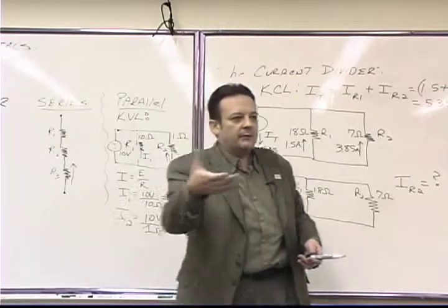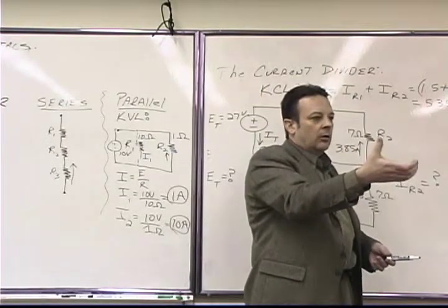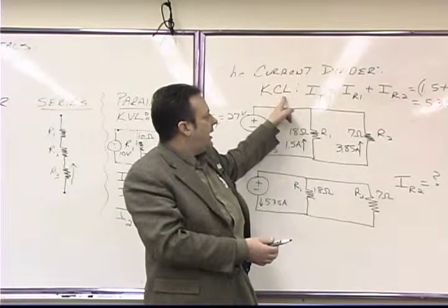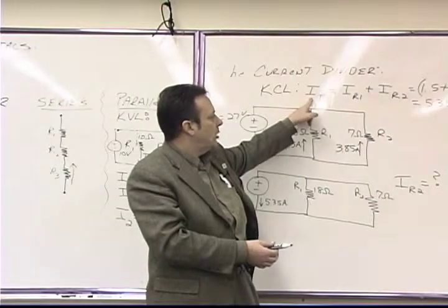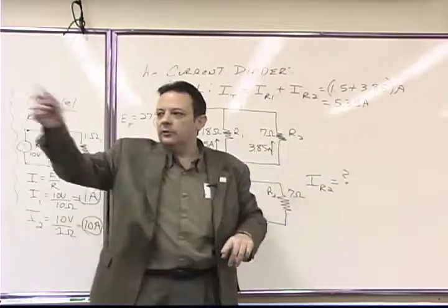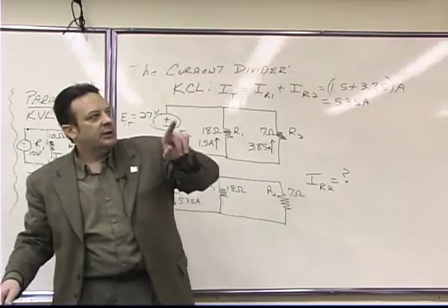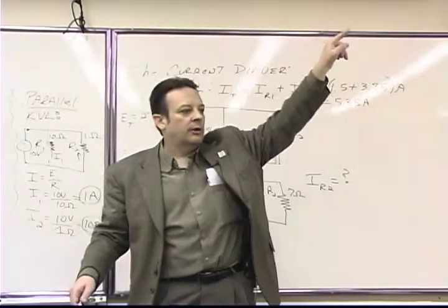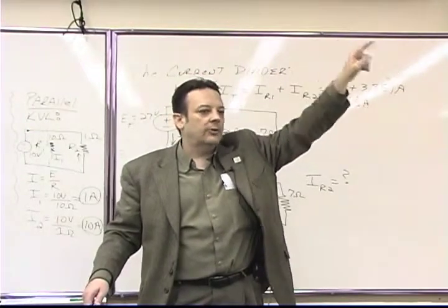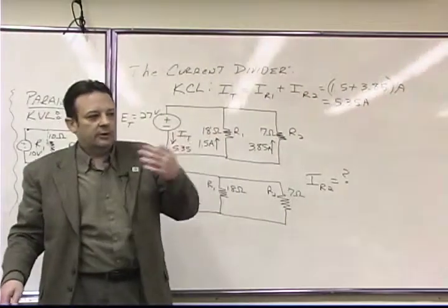And then when you go back to the panel, you'll check the current that's being drawn from the panel. And then by using Kirchhoff's current law, you'll find out that the total current being drawn from the panel doesn't add up to all the currents that are being used by your facility. Why? The reason is because some of the current is being stolen, and it's driving a whole bunch of load next door, and so that company obviously is not paying for it, and they're stealing, and it happens a lot.